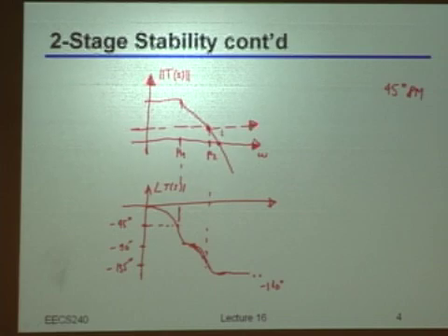And if I want a little bit better phase margin, then I should translate the omega axis even higher. And this impacts my gain. So it looks like the magnitude of T of S should be very small if I really want to stabilize or get my phase margin with just these techniques.